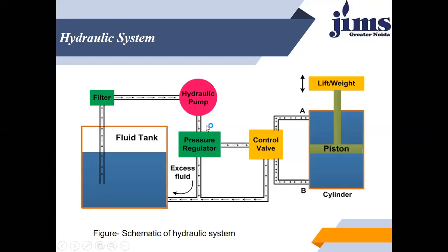pressurized liquid to the pressure regulator. So what will the pressure regulator do? After attaining that particular pressure value at the pressure regulator, the fluid is passed on to the control valve, and the excess pressure and fluid are returned to the fluid tank, right?